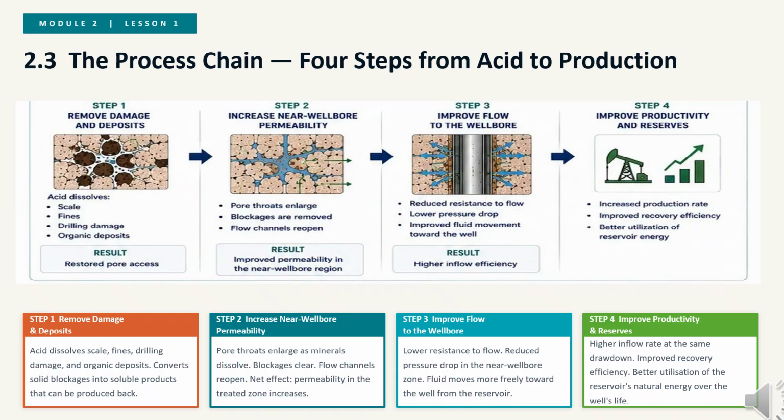First, acid removes damage. It dissolves scale, fines, and drilling residue. Second, permeability increases. Blocked pore throats reopen. Third, flow improves. Resistance near the wellbore drops. Fourth, productivity increases. Same reservoir, higher rate. This is not theory. The entire benefit comes from restoring a small zone of rock.